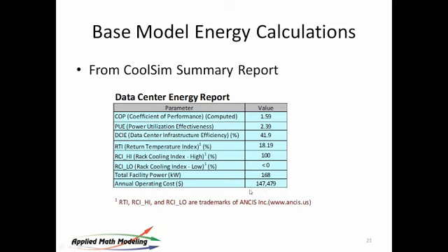Now, a couple of points here, Liz. COP is not constant. We know that. So as a design person or an analysis person, you have to pick a spot and compare to it. So in CoolSim 4 we have given you the ability to put in either COP or measured power at a point. It's only a single point. It's not a function yet. It doesn't vary over time, but it is a beginning. It is a start. And we think that makes sense. Now, over time, we'll get more granular.